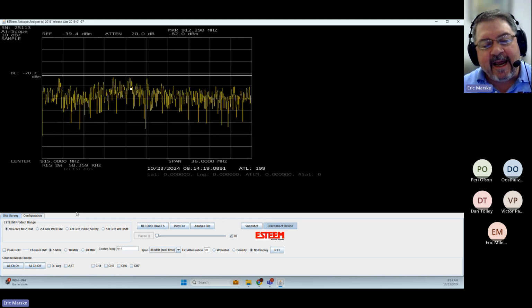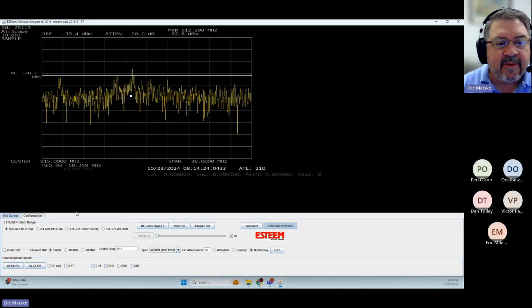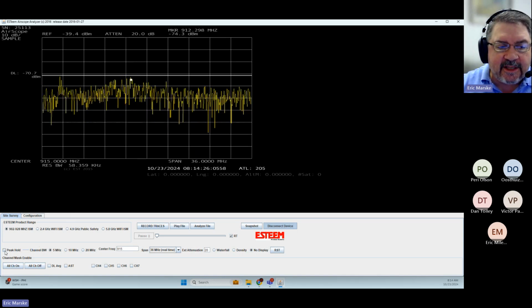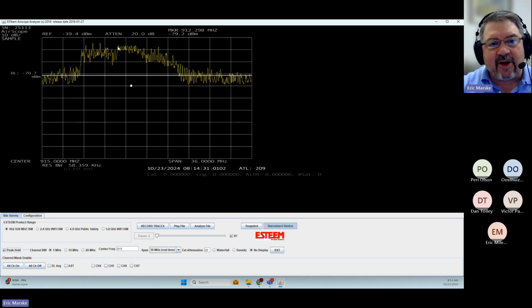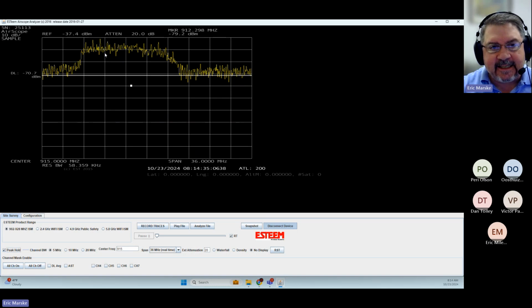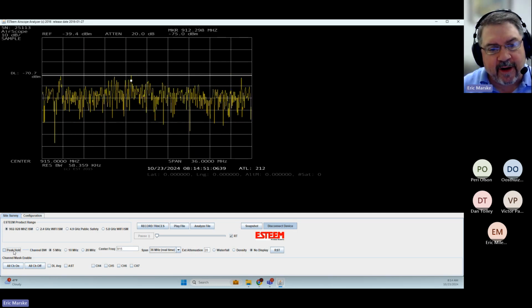Well, in a shared channel that's very difficult to do. Let me show you what I mean. So if I turn this on in 900 megahertz, essentially it's going to start adding up all of the different packets that it sees across that 900 megahertz spectrum, and we lose a lot of the resolution. We lose a lot of what we're seeing in that band. So where this really becomes important is peak hold is really used down into single channel transmitters.